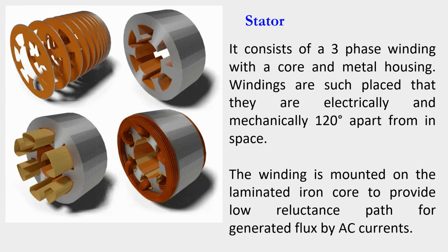Stator is the part to which three-phase AC supply is given. Basically it consists of a steel frame which encloses a hollow cylindrical core made up of thin laminations of silicon steel to reduce hysteresis and eddy current losses. A number of evenly spaced slots are provided on the inner periphery of the lamination. As you can see in the pictures, these are the thin laminations and these are the slots in the inner periphery.